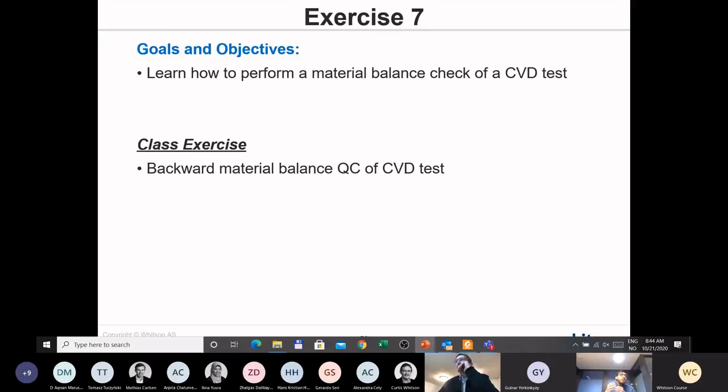If you have collected samples at each depth, you already have samples with a very wide range of composition, and doing a CCE experiment on all of those samples should be good enough for your equation of state model. But if you have only one sample collected from the field, and only one composition, you would try to do, for example, CCE and DLE or CVD and a multi-stage separator test to cover, to some extent, this wide range of composition space to tune your equation of state model.